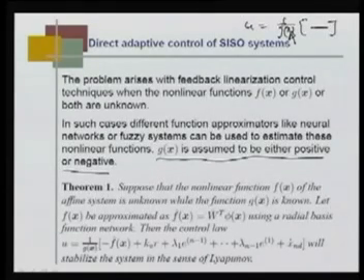Now, theorem 1 for direct adaptive control. What is direct adaptive control? I have to explain to you. Direct adaptive control means in this case we do not identify the system as a whole; rather the objective is how to select a parameterized controller, and the parameters of the controller are tuned directly as a function of the tracking error.